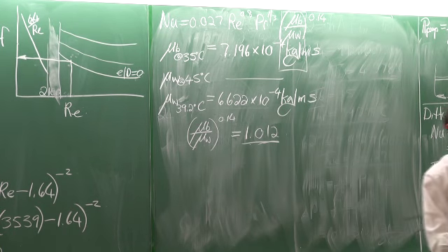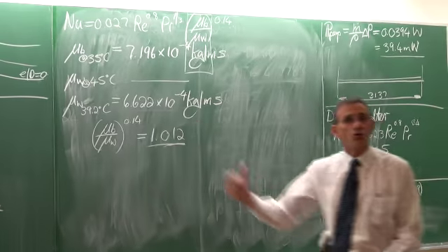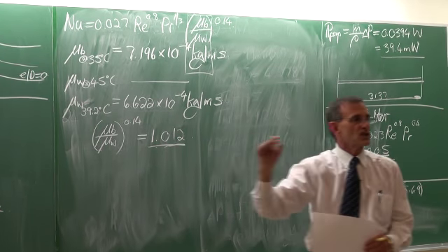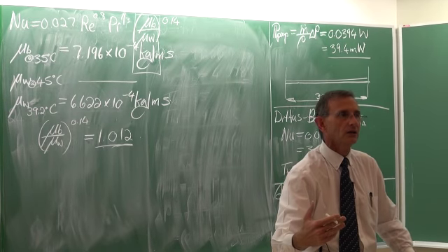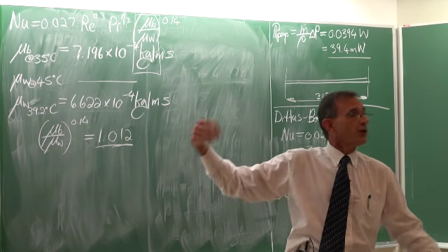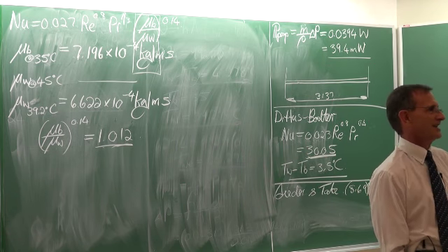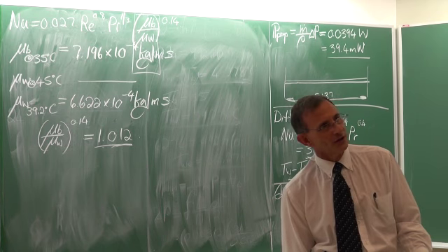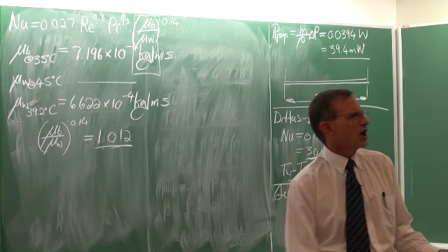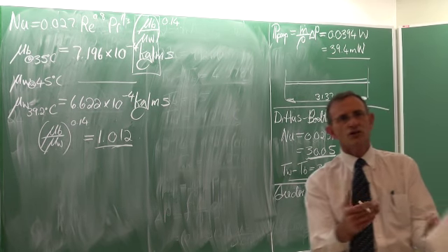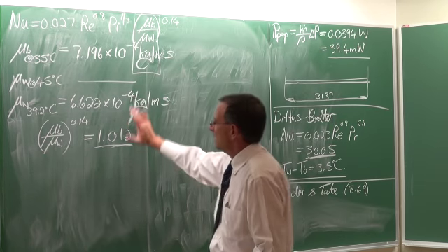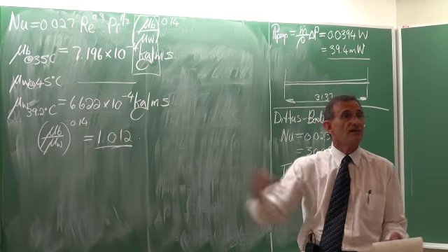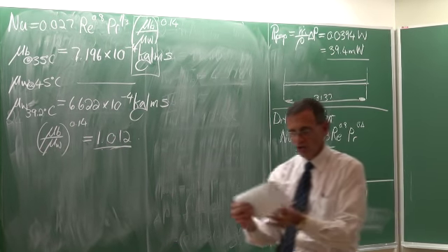Okay. What does it mean? It means that for this specific problem that we are doing here, the viscosity effects are not important. Therefore, it is not an appropriate equation to use. You don't know it before the time, you know it after the time. However, with things like water, typically 10 degrees, 20 degrees delta T, normally never an issue, but oils, mercury, and other stuff, then there will be very, very large ratios.